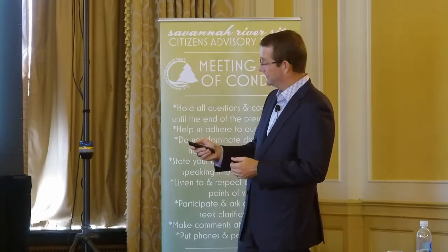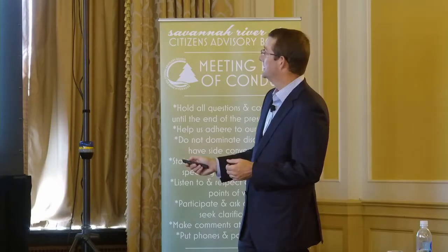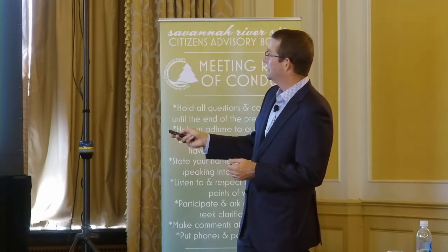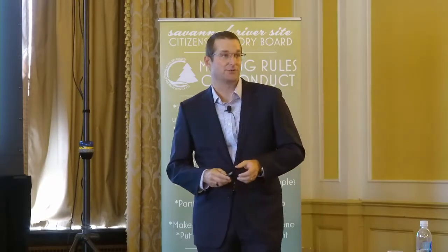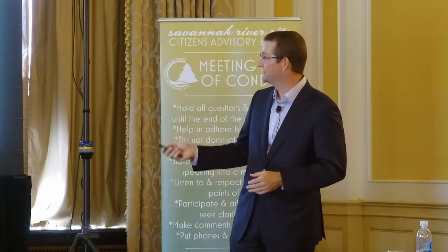Yes, and I did not speak specifically to it because I was in a hurry, but that bullet right there, one of the things we did in phase one of ELAW was went ahead and bought an extra mixer. And the mixer has a variety of pieces to it, and you can't see them all in the photo that I've got here. But out of frame, there is a transmission and motor, and those are split and set apart on different pads. So we can go in and do just a transmission and motor swap, or go do just a mixer body swap, and try to do it as quickly as possible.